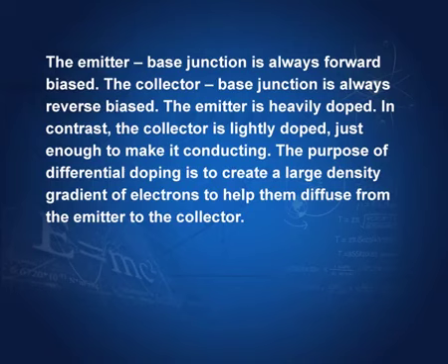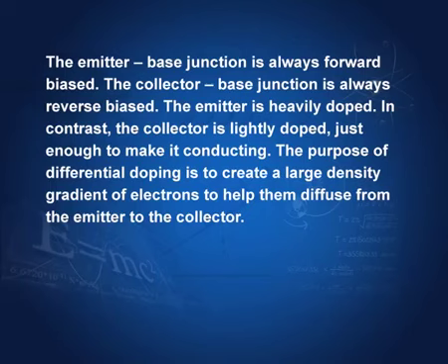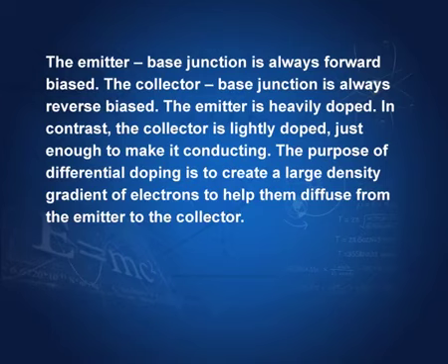The emitter is heavily doped. In contrast, the collector is lightly doped, just enough to make it conducting. The purpose of differential doping is to create a large density gradient. You remember that electrons will diffuse to a region where their density is lower than the density here. So, we create a large density gradient by doping them differently, so that electrons can flow from a higher density to a lower density. So, the purpose of differential doping is to create a large density gradient of electrons to help them diffuse from